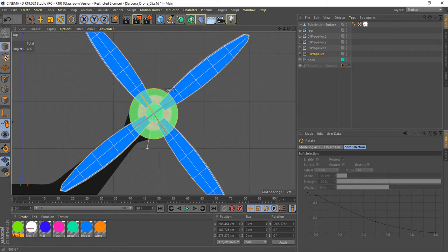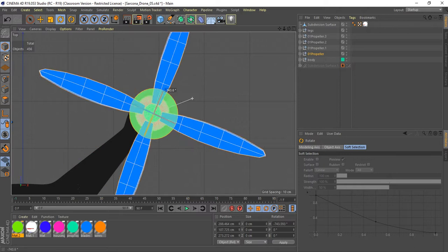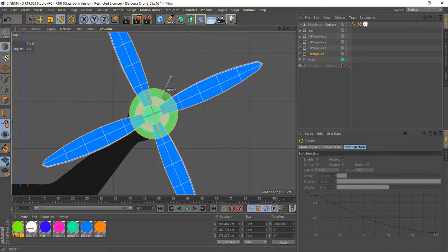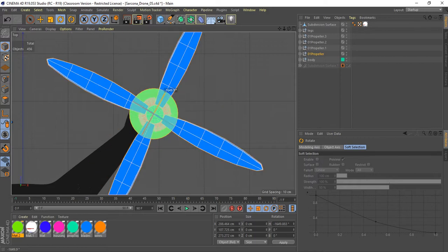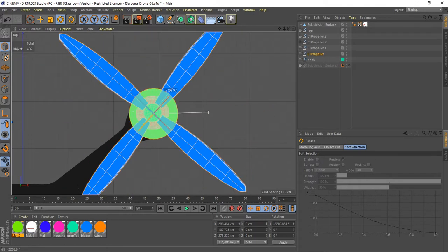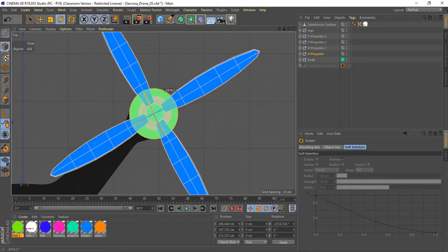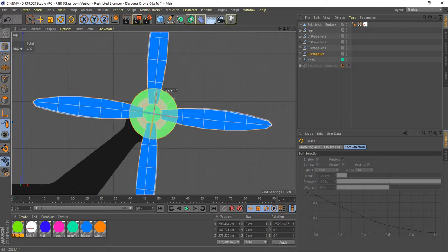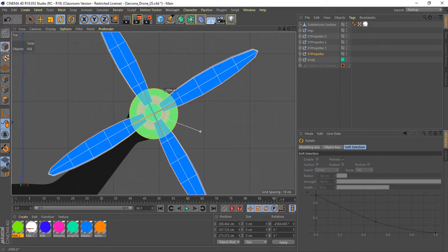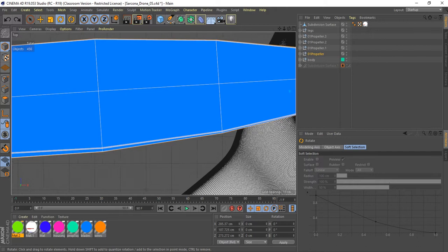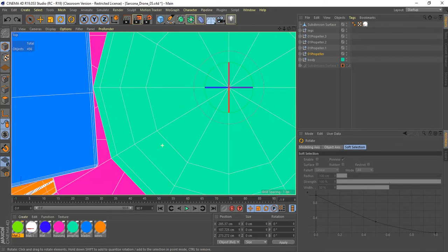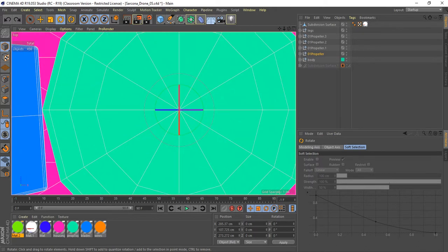Okay, now it might be hard for you to see that this is not moving correctly, but if you look at the pink part, which is the little base part, you'll see that that's actually moving off, like it's not perfectly rounded. Yeah, it's like warbling or whatever. So make sure your pivots are in the exact spot. You may have to zoom crazy far in here and make sure that it's lined up to that center line here and the center line there.